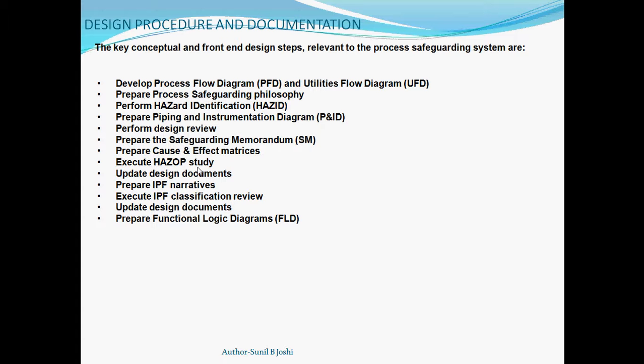Then we will execute HAZOP study. This will basically identify all the hazards that may arise due to any equipment operating outside its operating envelope. So all the keywords are applied and the major safeguards are then identified or are then required to be installed on the equipment as the outcome of the HAZOP study.